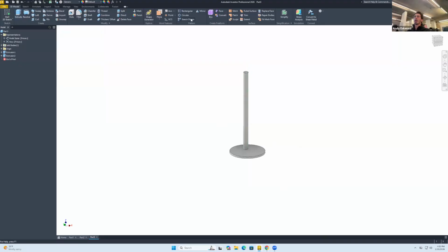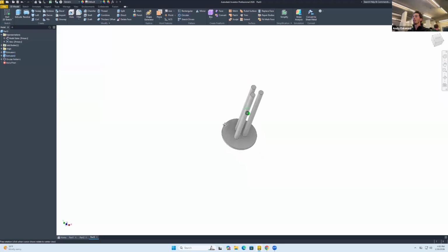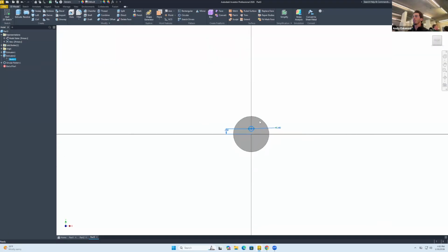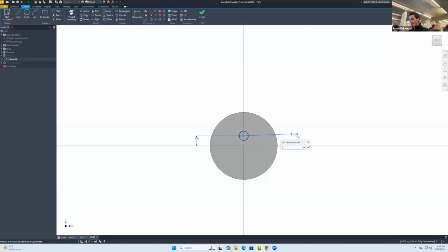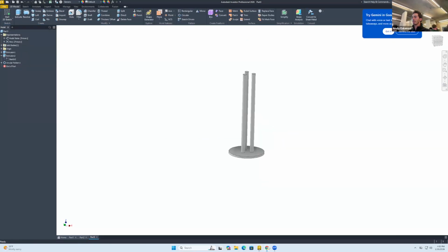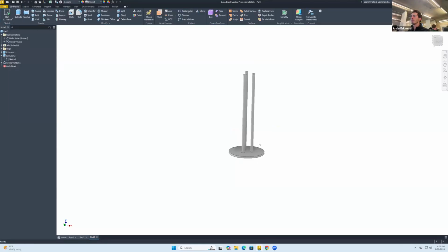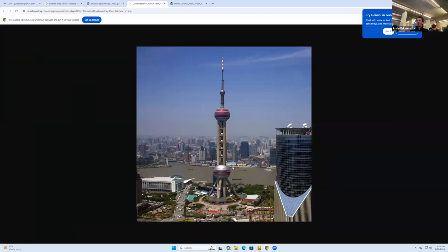Okay. So what can we do? Circular pattern. So I select this thing, I select this direction, and I'm gonna make 3. There we go. So very quickly, you have 3 pillars. In fact, I can always edit some of these things. I might make that 0.11 instead. There we go. Actually, I think it's even skinnier than that. Let's make that 0.08. I go to, okay. Good.